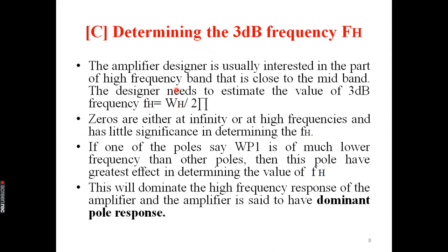But here we are giving a manual input. If you are considering an amplifier, we are giving an electrical signal which is coming from the transducer. Transducer is nothing but the mic. To the mic we are giving the speech signal, right? So we have to control the frequencies of the input signal till the cutoff frequency fH. The transducer should be designed in such a way that the electrical signal produced by it should not go beyond the cutoff frequency. If it goes beyond the cutoff frequency, the power output across the load will definitely come down below 50%.